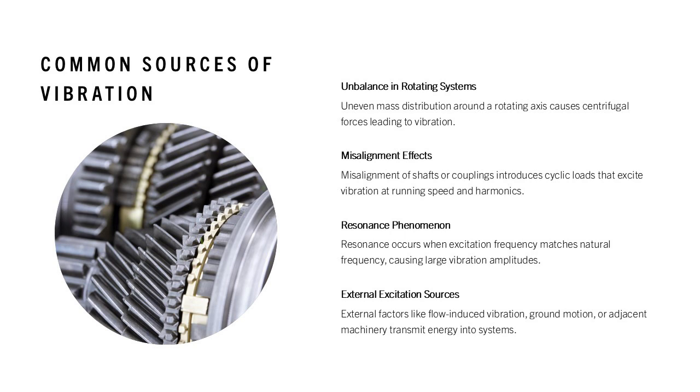Resonance is a particularly critical condition that occurs when excitation frequency aligns with a system's natural frequency, resulting in large vibration amplitudes. External excitation sources such as flow-induced vibration, ground motion, or adjacent machinery can also transmit energy into a system.